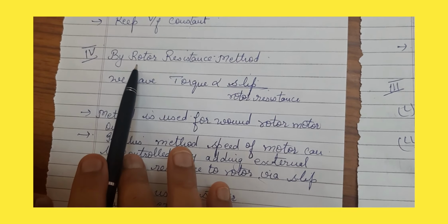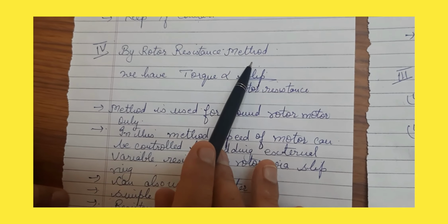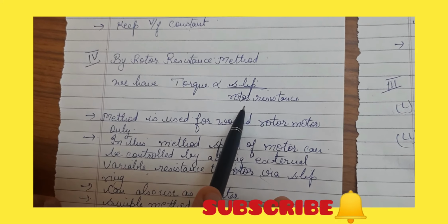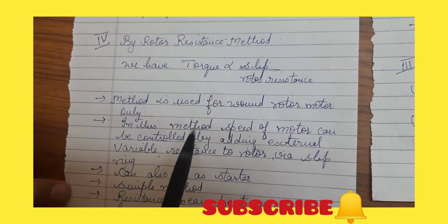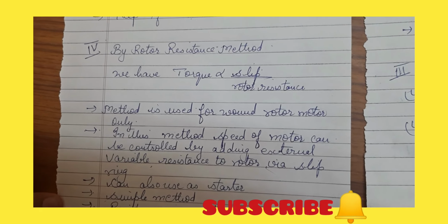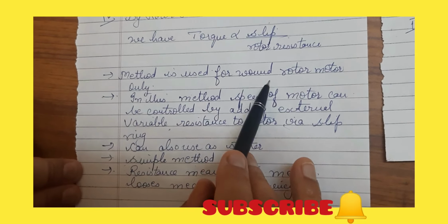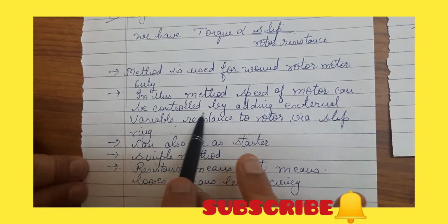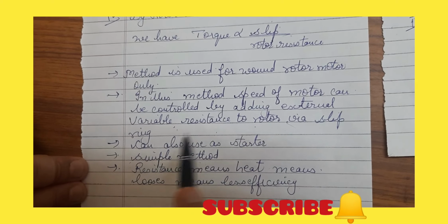The last method of controlling the speed of the induction motor is the rotor resistance method. In this, the torque is directly proportional to the slip upon the rotor resistance. We have discussed the definition of slip in the previous lecture. This method is used for the wound rotor motor only. The speed of the motor can be controlled by adding external variable resistance to the rotor via slip rings.